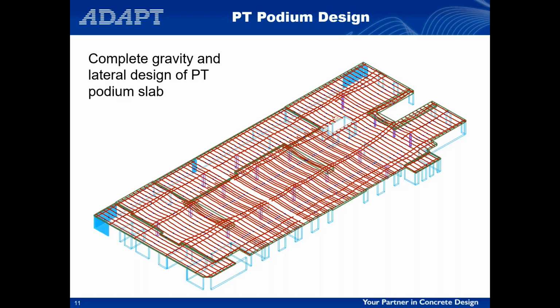So one thing you may want to consider and review in your design approach in your office is, because these podiums tend to be closer to the ground and very close to, obviously connected to, the foundation, you may choose to switch the default boundary condition when you're doing the PT podium design in Floor Pro, switch that to fixed as opposed to the rigid roller. So that's just one piece of advice to think about, and you can just do a quick comparison: take one of your models, run the two and see what happens.